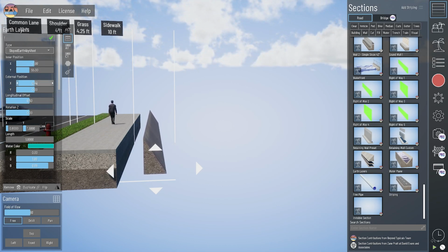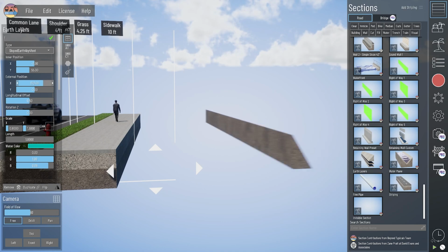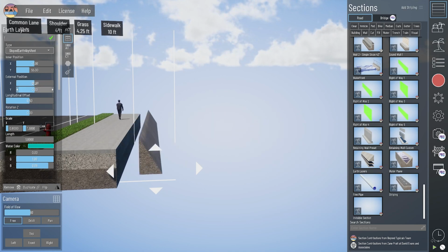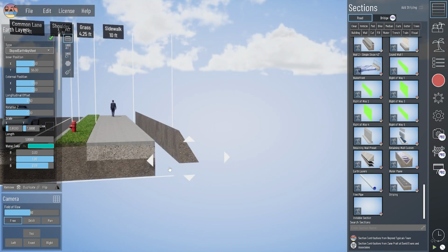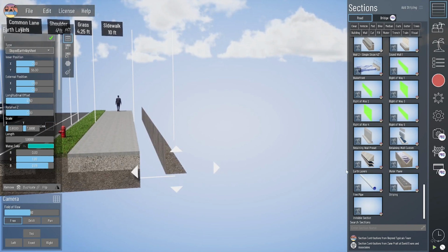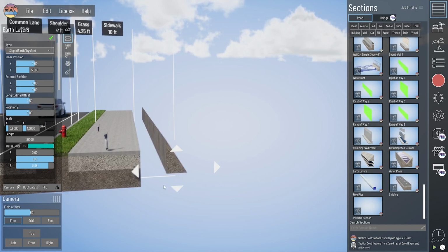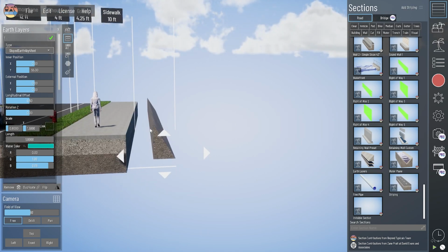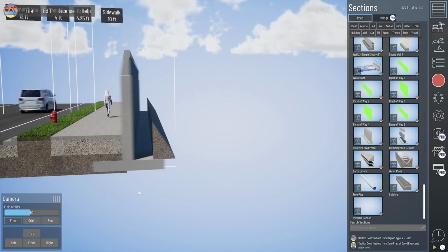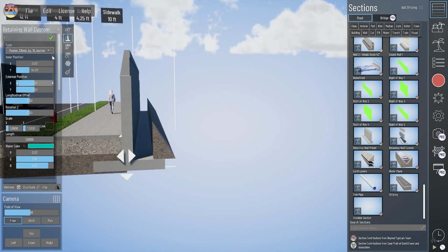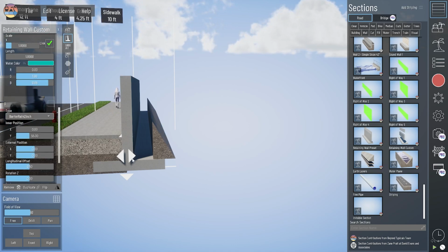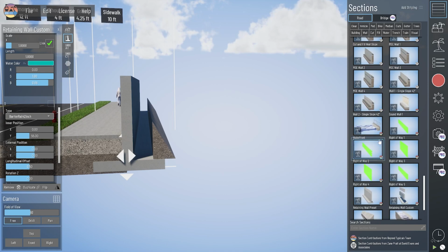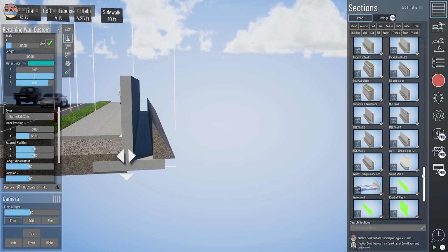So we get an X change or an external if we want to move it a lot further away from where that section is located. So I'll show you how this works. One way to implement this is if you have a retaining wall and you want to show some specific material behind it. So I'll go ahead and bring in a retaining wall custom here and make a few changes. I'm going to turn off the barrier rail up top, and then let's put in a cut slope behind that wall.